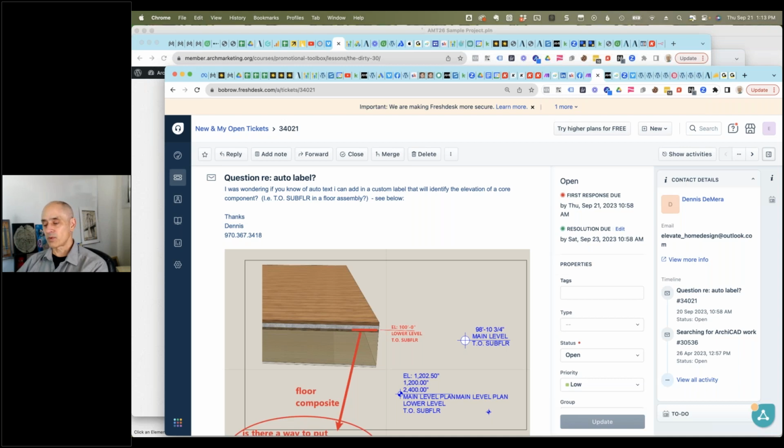So one possibility that comes to mind would be to have a flat slab for the basic covering of the unfinished ground, which could be sand and gravel and concrete, and then you use one or more roof pieces that have similar top material, concrete or asphalt, and you use a merge option in solid element operations. That way, with the roof elements, you can specify a slope, and you can even project where the roof elements would meet each other, so you have seams, the analog of roof ridges, hips and valleys and things like that.